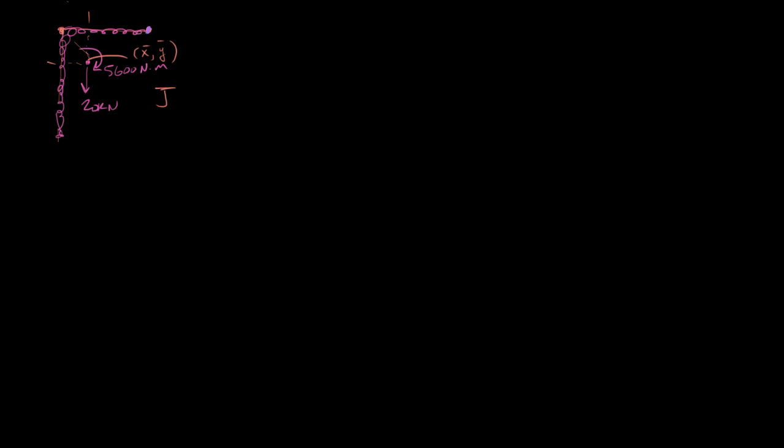We'll call this point A, and we'll call this point B. Those are the maximum distances from this centroid where that torque is applied, and that's going to be where the maximum shear stress is present. And so we're going to take a look at those points.